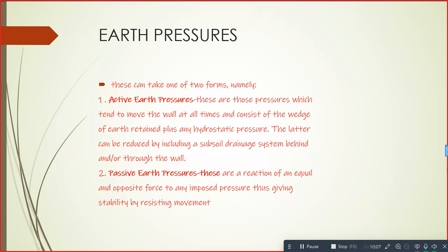The hydrostatic pressure can be reduced by including subsoil drainage systems behind and/or through the wall.